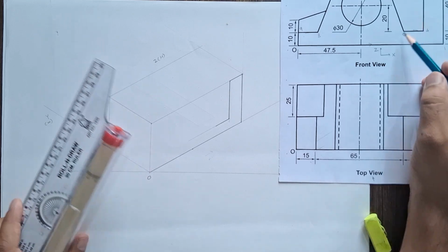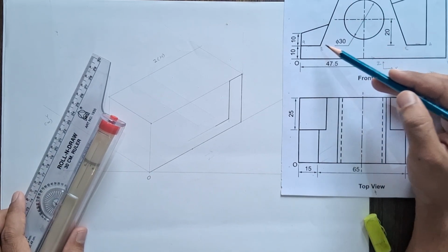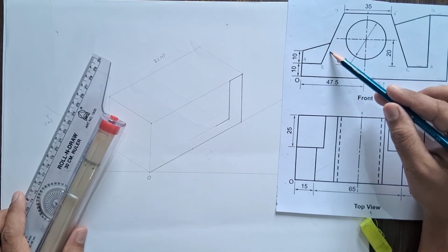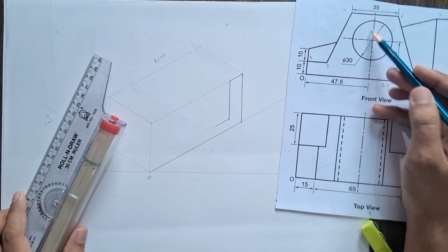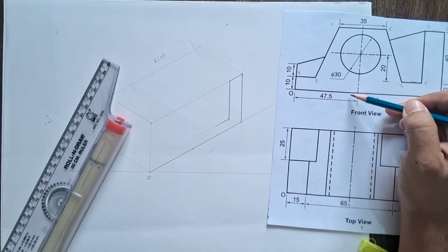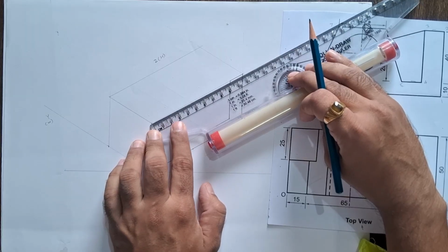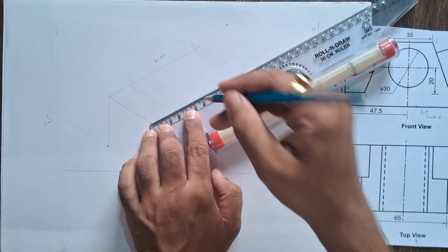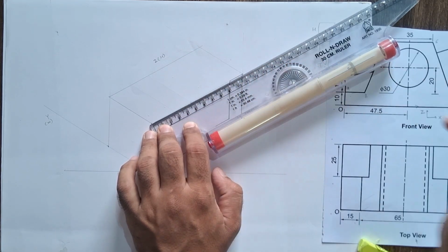Then after that, this 6, 5 and 7, 8 line, they are inclined lines, and these lines are called non-isometric lines. These lines we can't draw directly, but we know that the center of that 7 6 line is given, it is 47.5. So along the x-axis at a height 50 mm, we will mark 47.5 distance. This is 47.5 distance, and